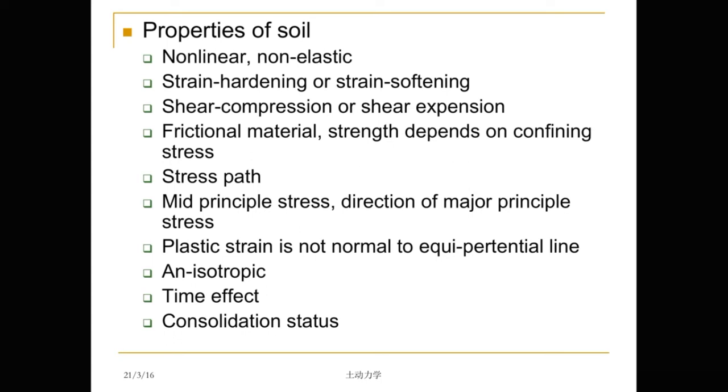But if you release your finger and you use another finger to touch the soil, you'll find the soil is so weak. This holding force is just the confining stress. The strength of soil just depends on confining stress. It is a behavior of a frictional material.